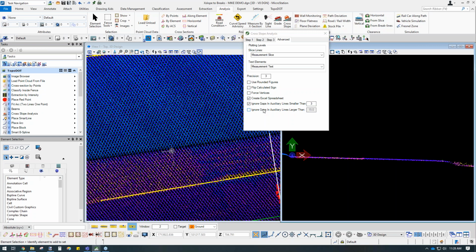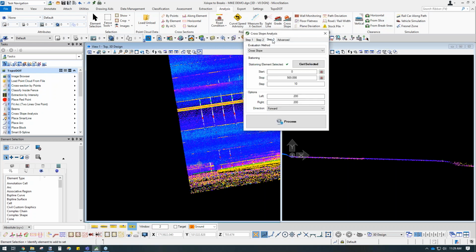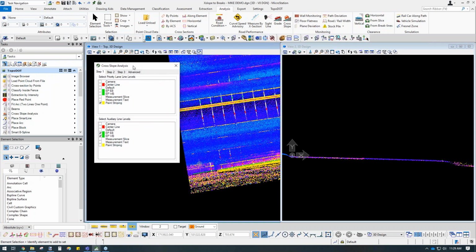And then the maximum gap, that's really if you're doing maybe ditches or something like that, or maybe you just want the shoulder slopes. So you'll have a shoulder slope on this side, and you'll have a shoulder slope on this side, but you don't really want to do lane lines. You'll specify a maximum. Say, okay, ignore anything that's more than 25 units or something like that. So that's basically this tool in a nutshell. I'll go ahead and end it here and pass things off to Alex, and then we'll open things up.